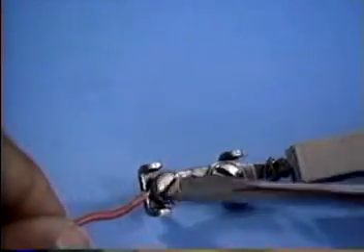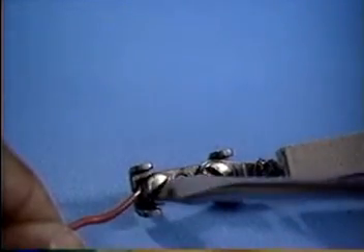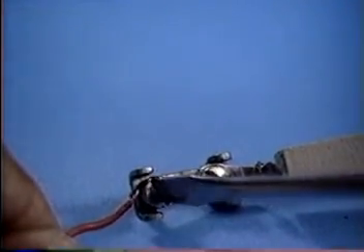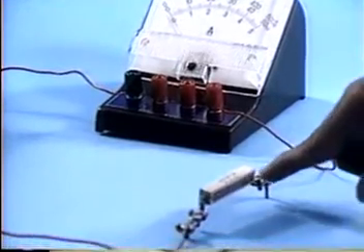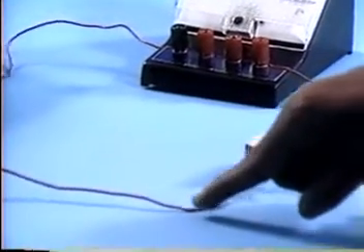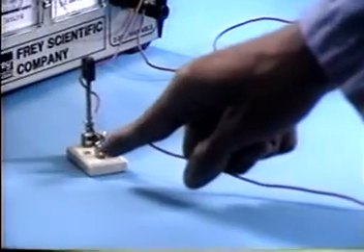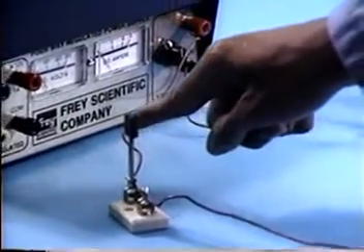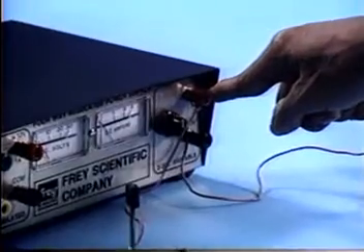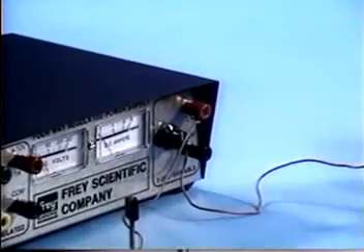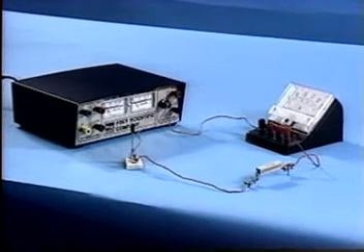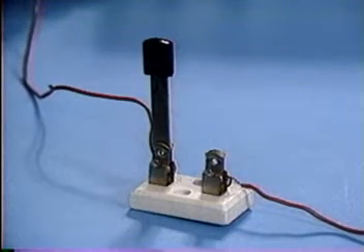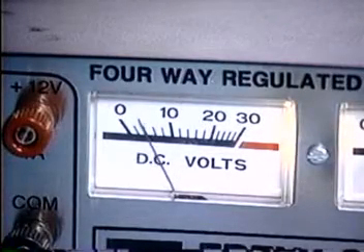Next, attach a 2 ohm resistor. This resistor has a simple screw-type post soldered to each end. Add another wire to the other end of the resistor and attach it to the knife switch. Finish up with a wire from the knife switch to the power supply. Now the circuit is ready, and it's time to turn on the electricity. But first, make sure the switch in your circuit is open before turning on the power supply.